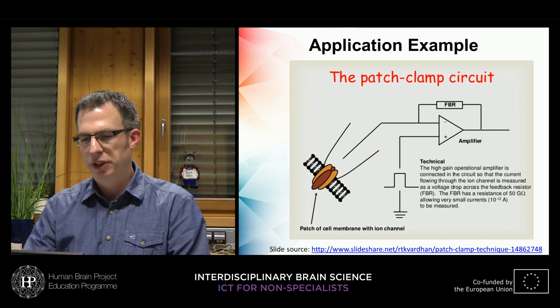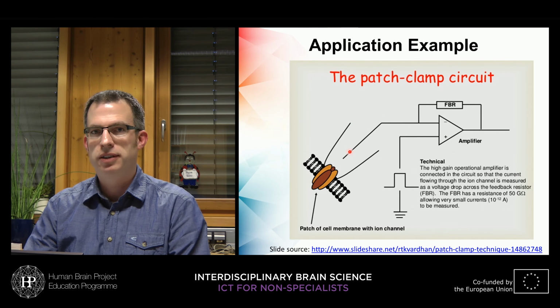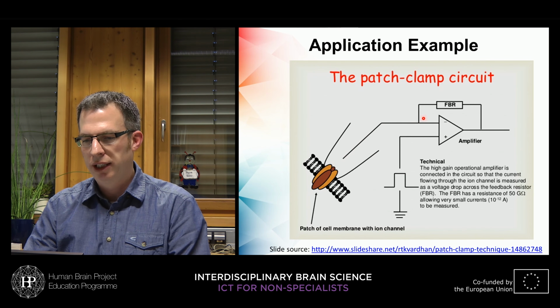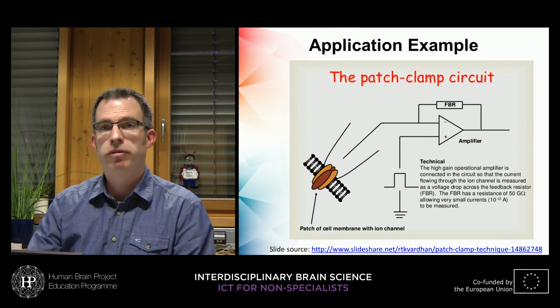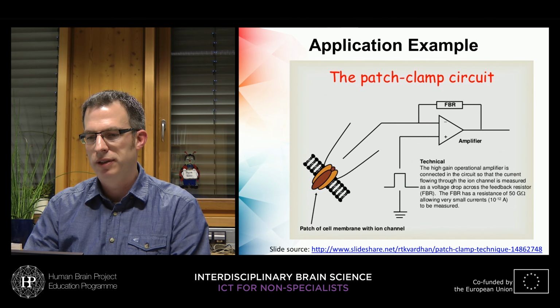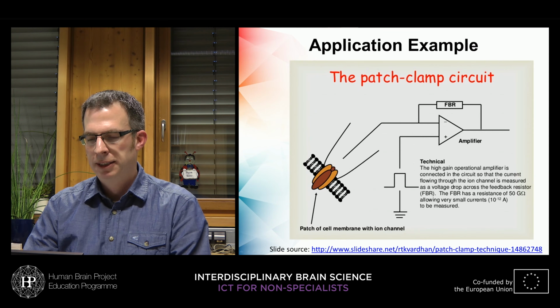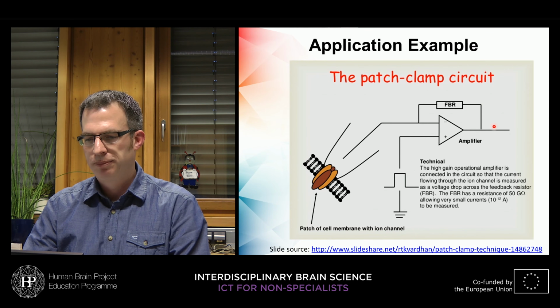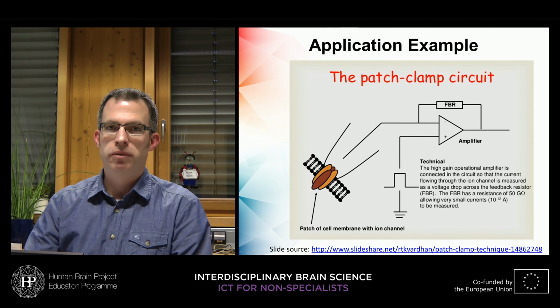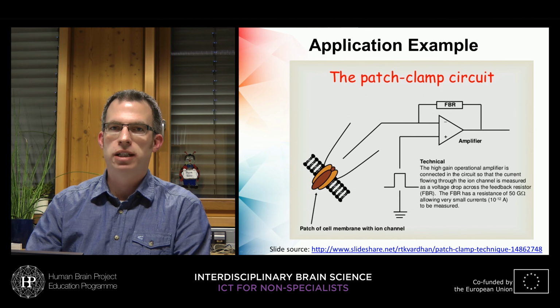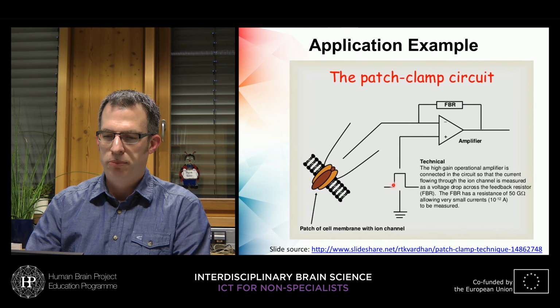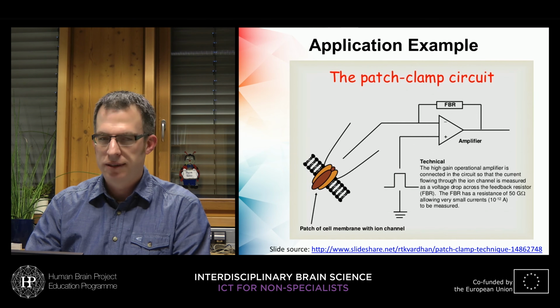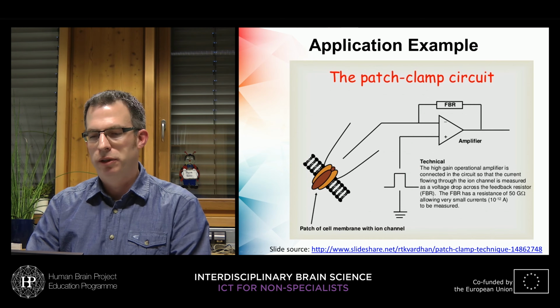and current can now flow into this probe and into a conductor that is inside this probe, and this is just connected to an inverting amplifier made of one operational amplifier and this resistor up here in the feedback path. So using this simple circuit, we can have an amplification of this current in the end, which causes a voltage drop across this feedback resistor up here, and we can even force currents to be injected into the cell by applying voltage pulses to the positive input here. That's a more advanced functionality of the system.